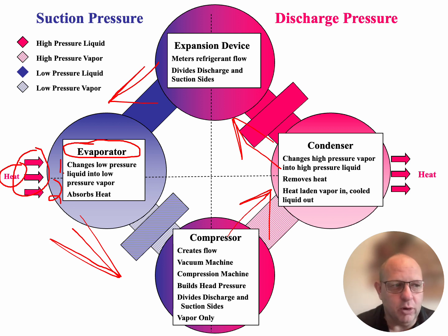An employer I used to work for had a great saying: refrigerant doesn't use out, it leaks out. So once we have leaked out the refrigerant, the process of heat transfer can no longer take place within our system. So that's what's going on when you end up losing refrigerant out of your system. You actually lose the ability to move heat throughout the system because the transfer liquid, such as the refrigerant, isn't in the system anymore. So we can't absorb that heat and we can't reject that heat as it's moving throughout the system.